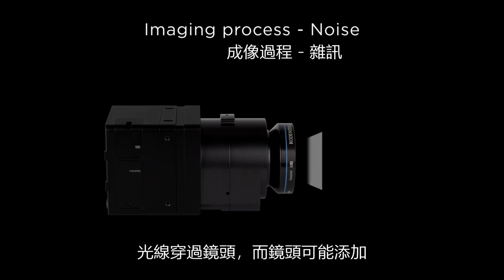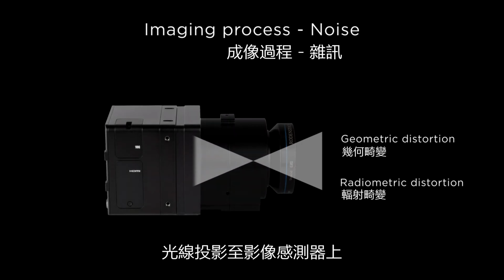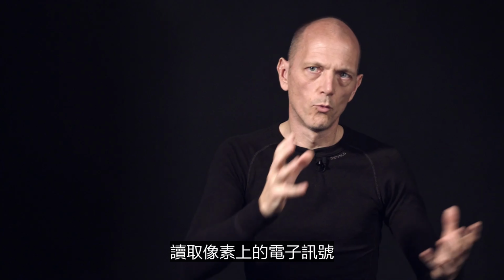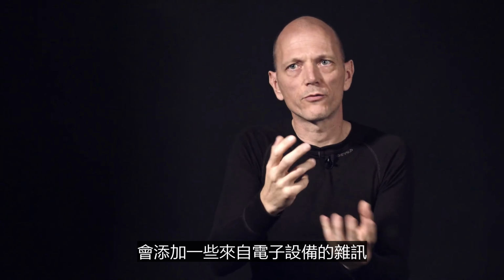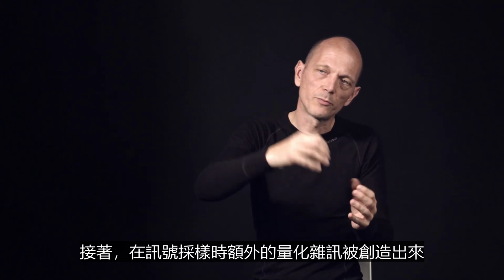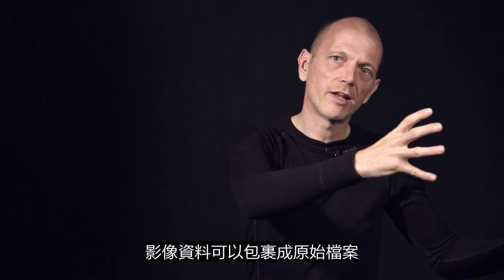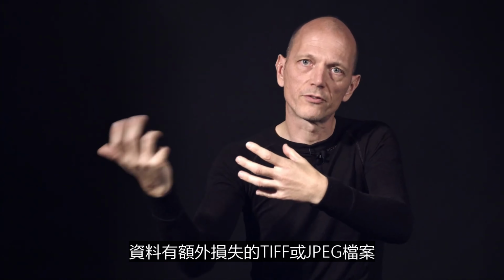The light then passes through the lens, and the lens can add geometric or radiometric distortion. The light is projected onto the image sensor and turned into an electrical signal, adding additional types of noise. Reading the electrical signals out of the pixels and amplifying them will add some noise from the electronics. And then additional quantization noise is created as the signal is being sampled at, for example, 8, 12, 14 or 16 bits. The image data can be packaged into a raw file containing the unmodified sensor data, or it can be processed further into a TIFF or JPEG with some additional loss of data integrity.